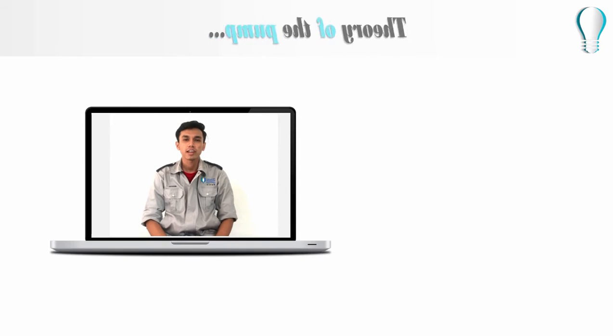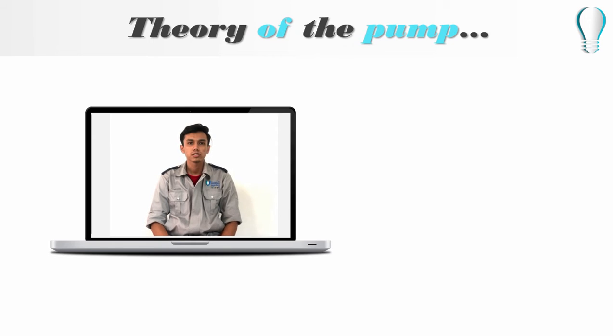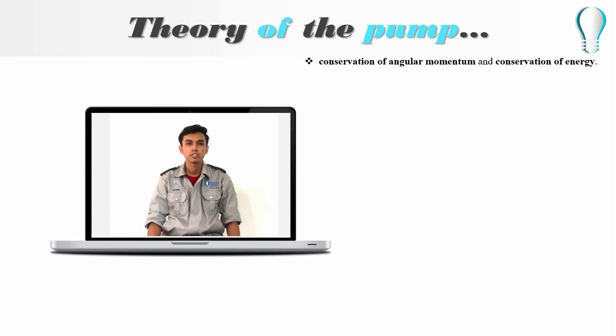And now, in this slide, I will present the Euler turbomachine equation. From the previous slide, we already know about the introduction of the centrifugal pump. So in this slide, I will talk about the Euler turbomachine equation, or sometimes called the Euler pump equation. It plays a central role in turbomachinery as it connects the specific work Y and the geometry and velocity in the impeller. The equation is based on the concept of conservation of angular momentum and conservation of energy.